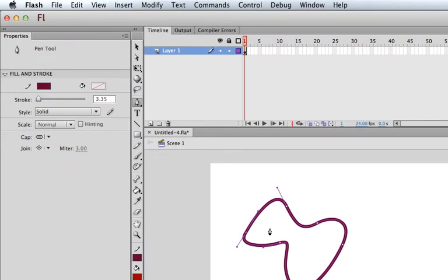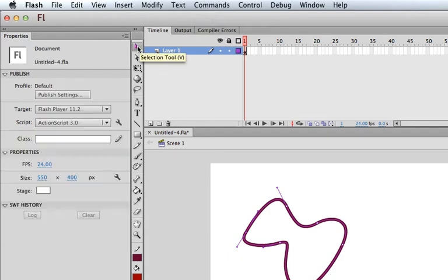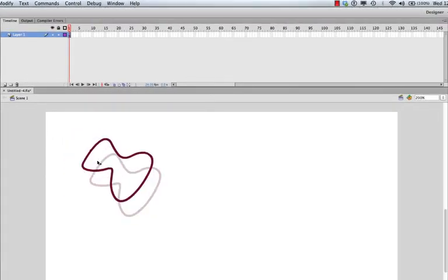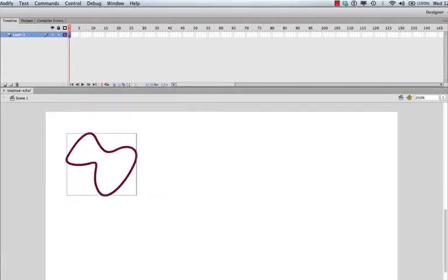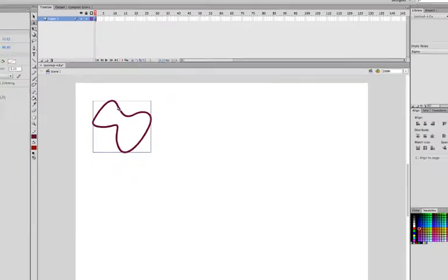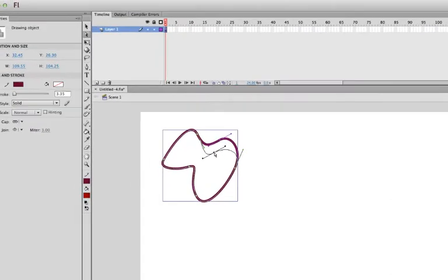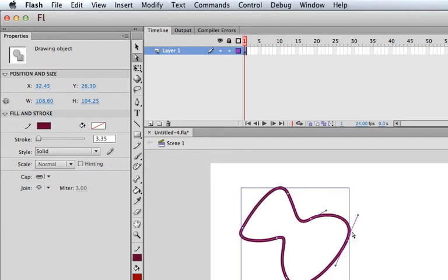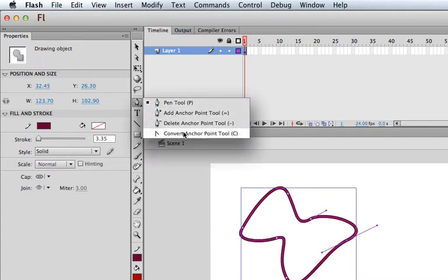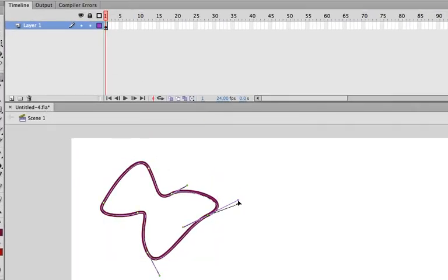it is amazing. Right? We love the pen tool. We've learned to love it. We do lots of fun stuff with the pen tool. Again, I drew in object mode so you can move it with the selection tool. If you use your sub-selection tool, which is the white arrow tool here, you can also click on the individual anchor points, move those around just like we're used to. You can move the handlebars, the directional handlebars here, to change the curves, lengthen and shorten, all that good stuff. You can also use the convert anchor point tool, which we're used to, to break those curves.